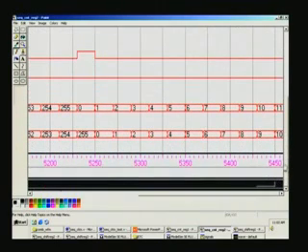Once again, the time base you can see. In fact, it has taken plenty of time because it has gone through 0, 1, 2, 3, etc. up to 255. It has counted 256 rather totally. So many clock pulses it has gone through. So you can find out how much it is here, around this, right? But we started not on 0, but after a time lag. So you can find out, I think 20 nanosecond we did, 20 into 2 to the 6, plus some extra time because reset was applied and so on. You can always go and verify this.